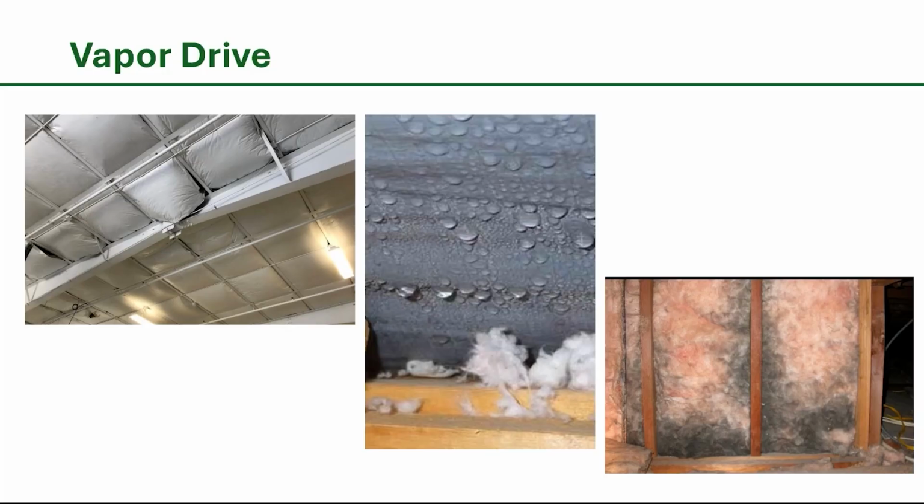That black stuff there is kind of a telltale of where the air and water have been moving through the insulation. And it's always where you'd expect it, predictable. Down at the bottom where it's not sealed very well, and along the studs where you have a lot of penetrations of screws and other things, allowing moisture and air to get through.